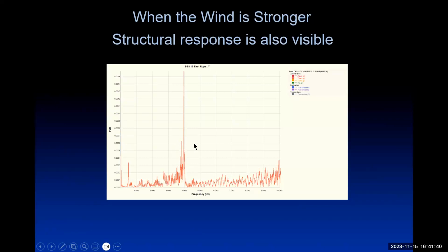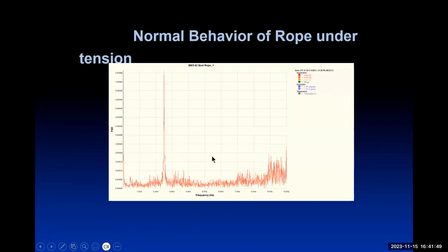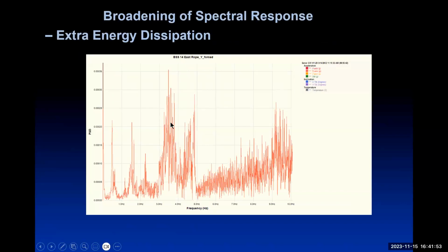Now you can see here we've got the main bridge frequency, and we've also got the hanger frequency as well. This is one of a different length, and this is one which is not fastened well. I think you can see quite well what the problem is there. As the amplitude changes for this hanger, then you get a different frequency. Same way you do in earthquakes.